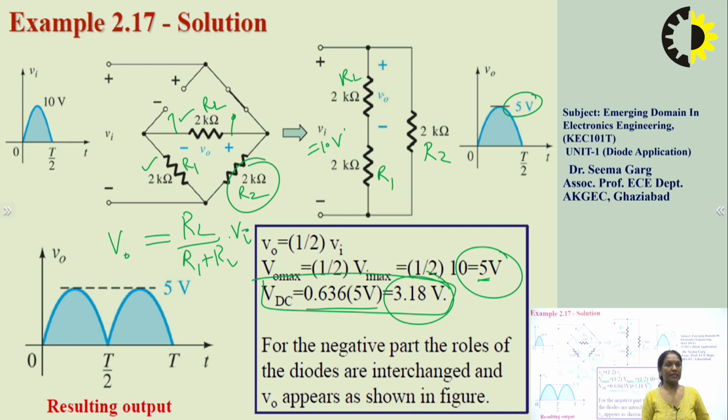That we will discuss in the next lecture. Zener diodes are highly doped PN junction diodes which operate in the reverse bias condition. If you connect the Zener diode in forward bias, it behaves as a normal PN junction diode. But if we connect it in reverse bias, then it acts as a voltage regulator.